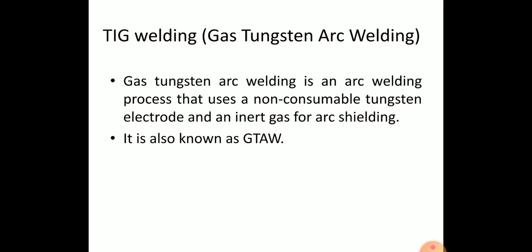Argon is normally preferred over helium because it requires a lower arc voltage, easier arc starting, and provides a smooth arc action. Helium is uneconomical and lighter. Helium can withstand higher arc voltage, so it is used where higher heat input is required. Sometimes the active gas carbon dioxide is also used as it is more economical. It requires slightly higher current. It is normally used only with DC with positive electrode, whereas both argon and helium can be used with AC as well as DC welding power sources.